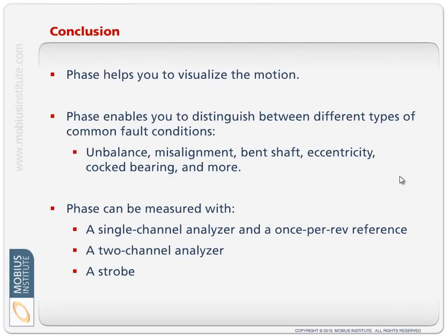That tells us about everything from unbalance to misalignment, looseness, resonance, all sorts of fault conditions that can be picked up thanks to phase. And we may even see, or we often do see, changes in the spectrum, but making sure that we've correlated correctly what those changes are to what the fault condition is potentially means the machine failing or not, or getting unnecessary work done, that sort of thing.